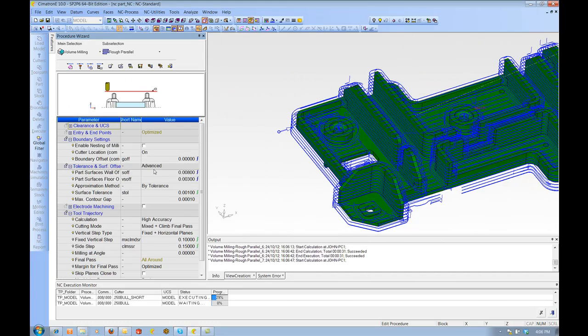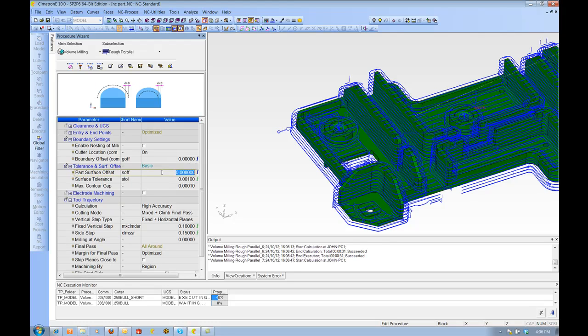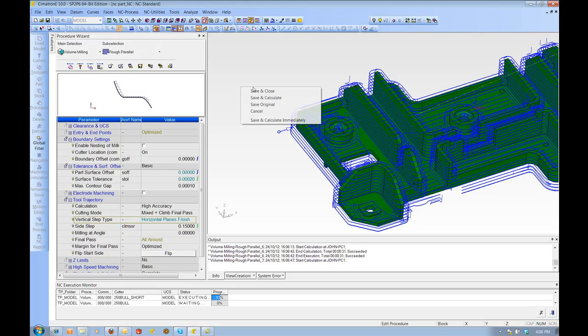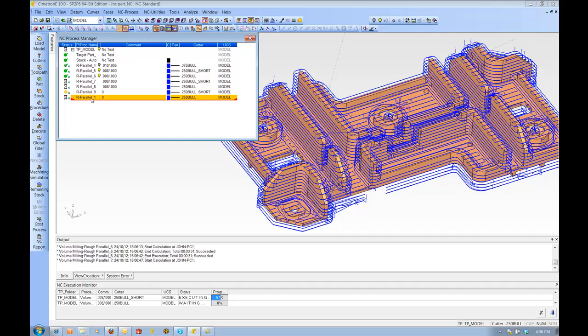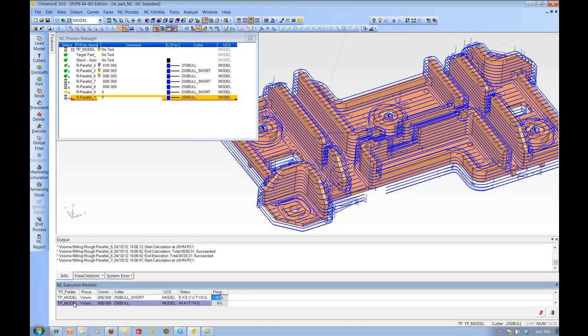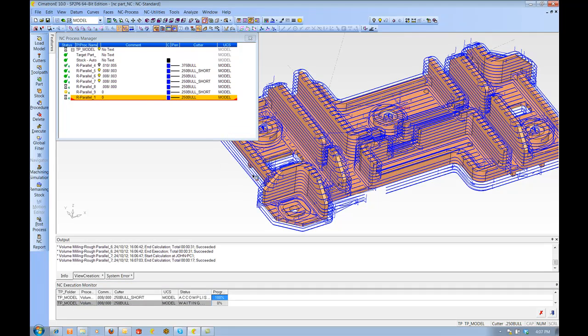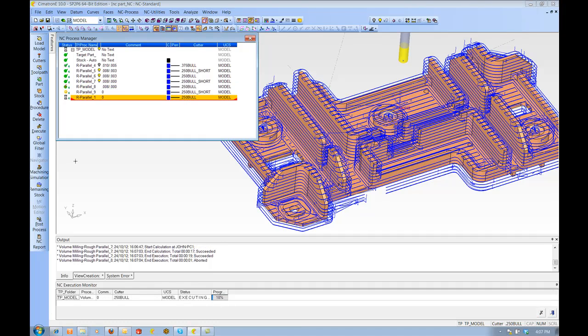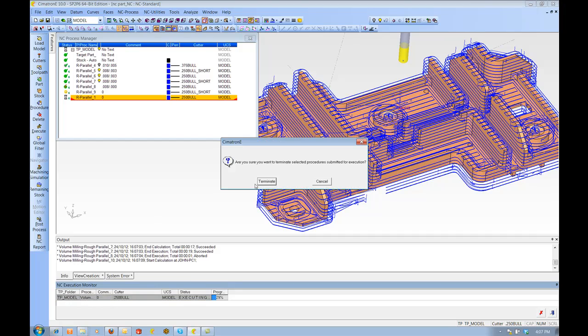And this is really what's neat about this, is that the result of this one is going to be just like we spent a lot of time doing a lot of chaining to do 2D machining, only we're not spending a lot of time doing chaining, and we're not giving a lot of care to having all the Z levels be right. We're going to let the software take care of all of that for us.